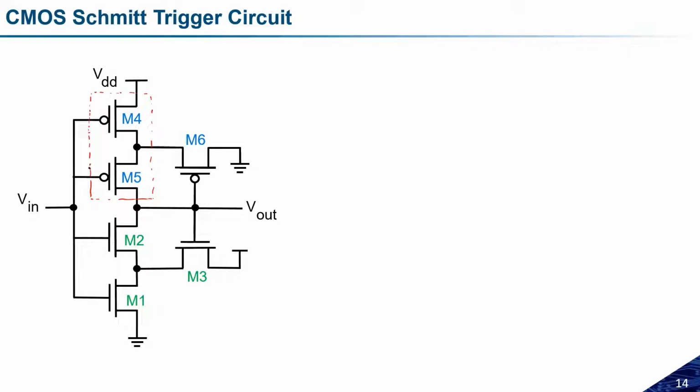Net resistance will increase, yes. On resistance will increase, yes. This concept is not in our scope, but it is known as the stacking effect. With stacking, we can effectively increase the strength of the pull-up network.